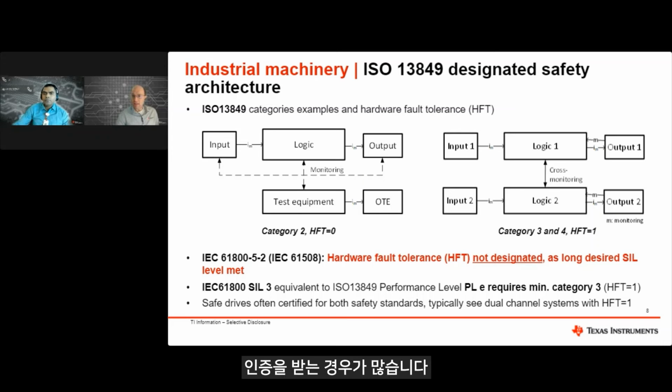For the safety of processing, the microcontroller architecture with redundant cores is optimized for both automotive as well as industrial safety systems. For automotive use cases, the dual-core lockstep architecture provides comprehensive coverage of the faults within the processing unit. In multi-core devices, the C28x and the CLA cores offer diverse architectures for implementing effective reciprocal comparison with high confidence and reduced system development time. In addition, periodic testing of the CPU core in the long-running industrial environment is supported by online hardware-based self-test. This helps in avoiding accumulation of faults, which is a key requirement for ISO 13849 PL e, which is an HFT equal to 1 and dual-channel system architecture.